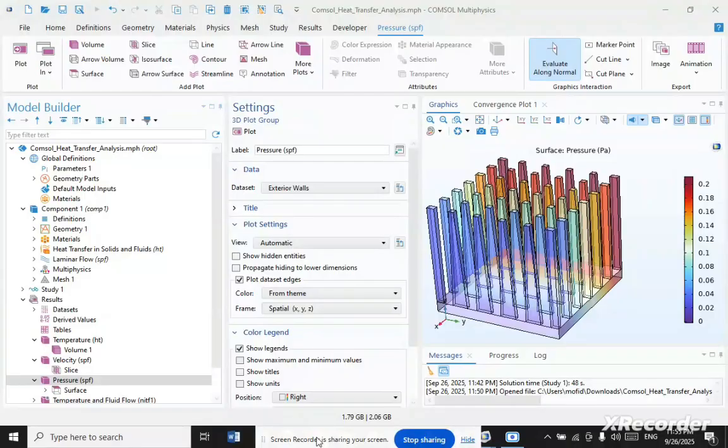Furthermore, there is a considerable scope for innovative pin fins, as pin fins like open rings and lattice structure have shown effective cooling compared to conventional pin fins. With recent advancement in various technologies, the heat flux has been increasing drastically over time, and it may exceed 1000 watt per square centimeter in the near future.